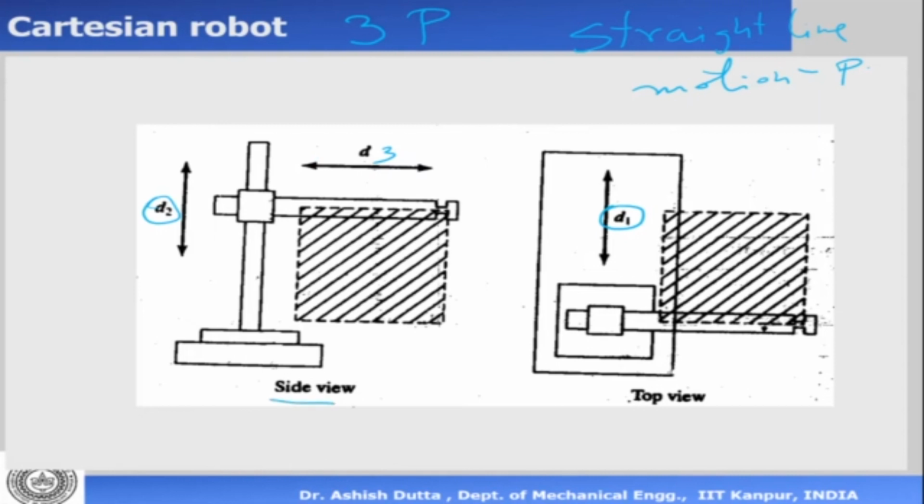Let's start off by looking at the side view. Now let us assume that this link is fully extended as shown here. So this is the maximum condition in which it is extended. It is till here, it can come till here. Now I can move it backwards, the link, when it goes back like this. It will come to this point. So when I'm moving this joint number 3, I'm retracting the joint in this direction.